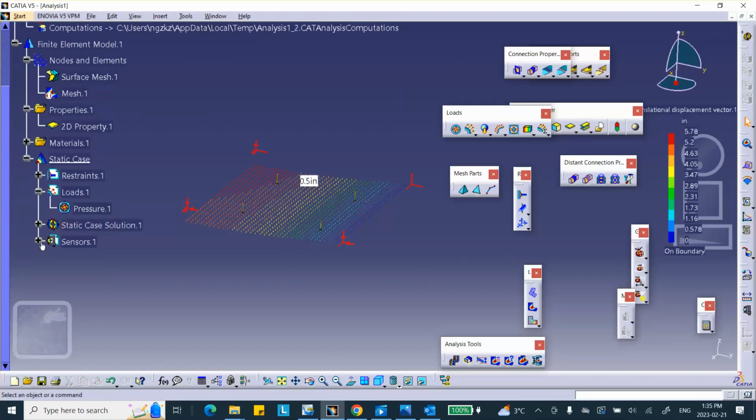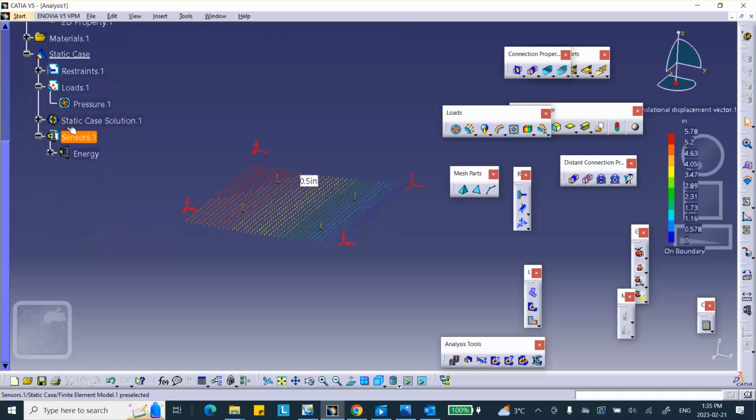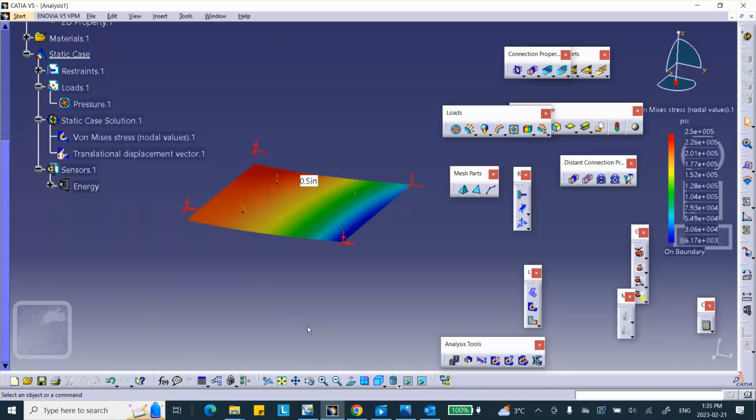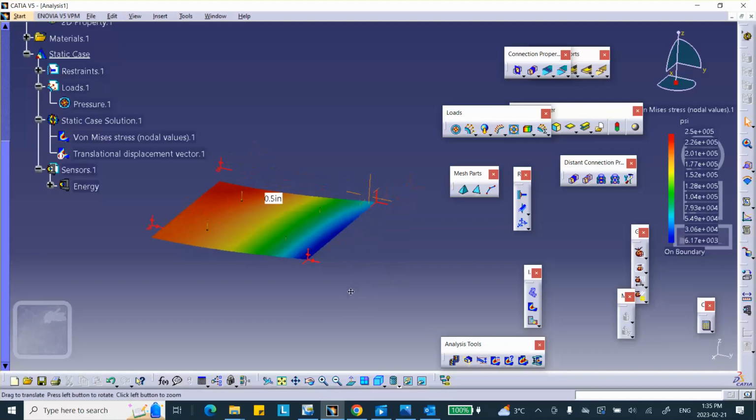Let's look at the stress one more time. Stress right here. Deactivate this. Activate the stress. Yeah, that is 200,000 psi. So that is pushing it close to the yield strength. Obviously, it depends what kind of a steel you've got. If it's structural steel, let me write the Young's modulus one more time. 30 million psi, and I knocked down. Yeah.